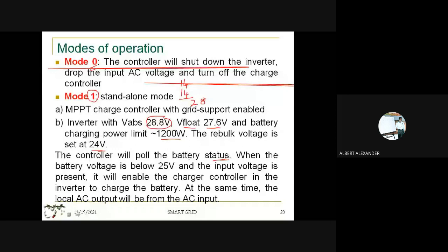Okay, because I cannot take the inverter output voltage as a reference, because you can control the inverter output voltage with the help of your PWM. My PWM may or may not ensure the control of the voltage obtained across the output gate, so I cannot take the inverter as a reference. I cannot take a solar PV as a reference, because I cannot give any kind of feedback. So here we can understand the battery is the only terminal for a microgrid work, where we can see whether the power is coming from the solar PV or the power is diverted to the grid or not. So the decision can be made only by collecting the status of the battery at every interval of time.